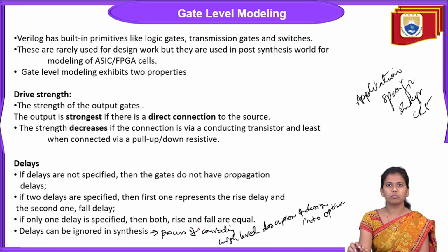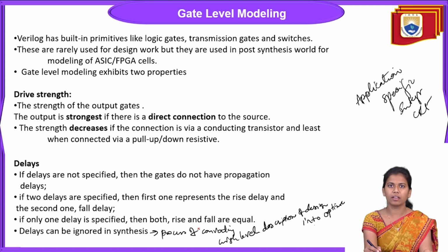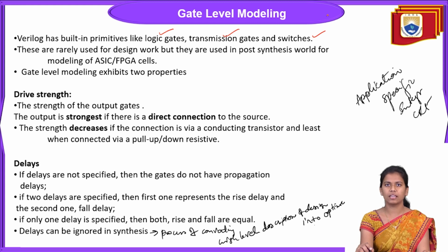Coming to gate level modeling, we all know that Verilog has built-in primitives like logic gates, transmission gates and switches, isn't it? So this Verilog has a library, and particularly in gate level modeling, we construct or design the circuits in terms of logic gates, transmission gates as well as switches.